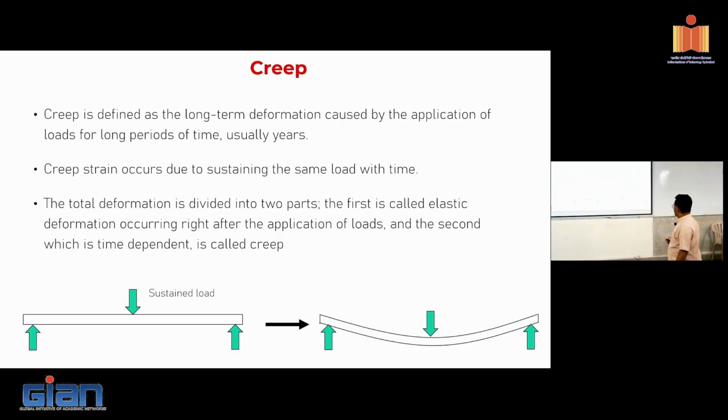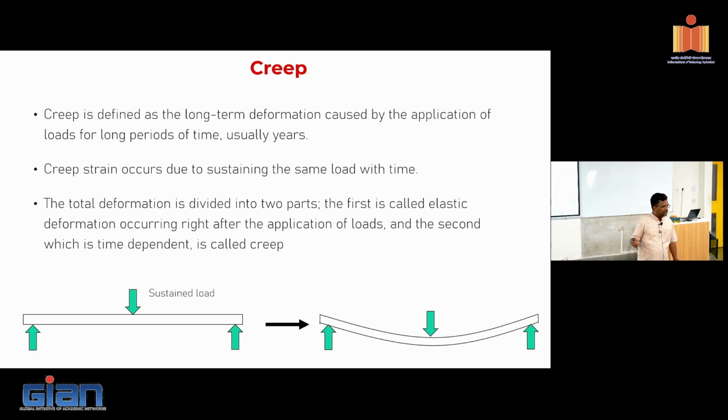Okay? So anyway, what you see here is, under sustained load, say I apply some load, if the system is elastic, depending upon the support conditions, you can derive what the elastic deflections are going to be. If the loads are kept the same, over a period of time, you will find that the deflection will keep increasing. So why does it happen?